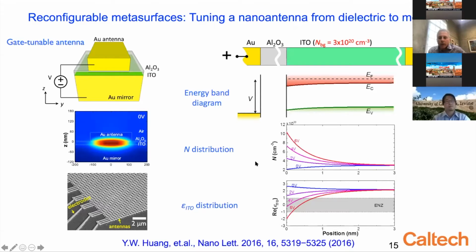We can adjust the carrier density of the material by chemical doping such that accumulation of carriers near the gate dielectric region, very similar to the principles of operation of a transistor, modulate the permittivity in this region between approximately +1 or 2 to -1 or 2 in this few nanometer region. And this is a region, of course, where the mode interacts very strongly with this tunable permittivity medium.